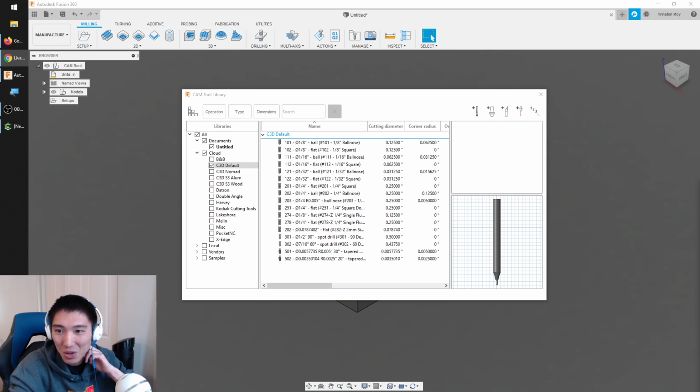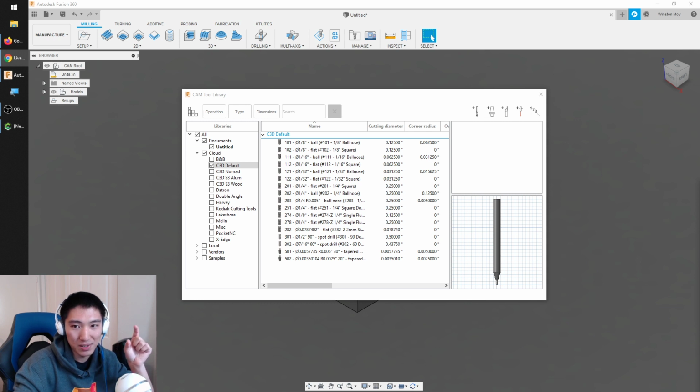Looking forward to seeing the new Carbide Motion. Is there a way to set up custom third-party touch probes? There is not, unfortunately, just because our probing interface is sort of hard-coded to a 25 millimeter tall probe. If your third-party probe is that tall, great. If not, I don't think we're going to plan on opening that up just so you can input whatever the thickness of your probe is.